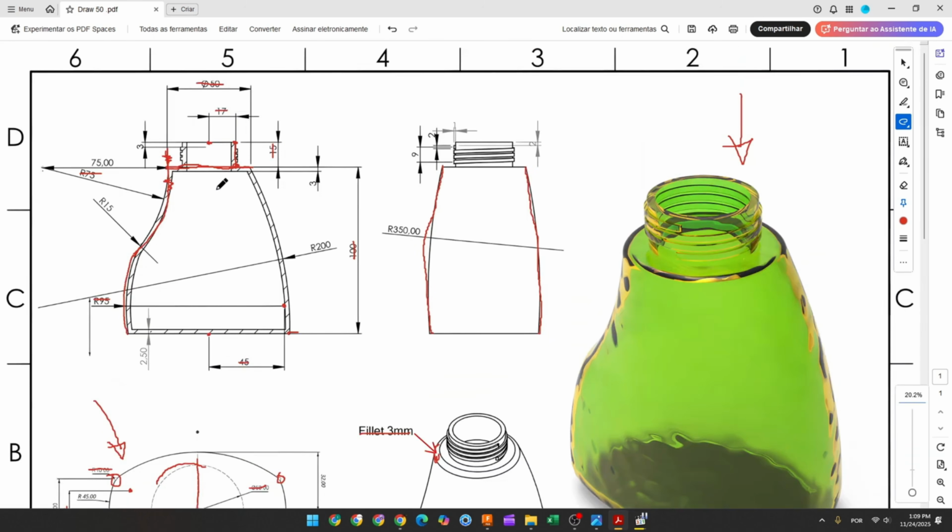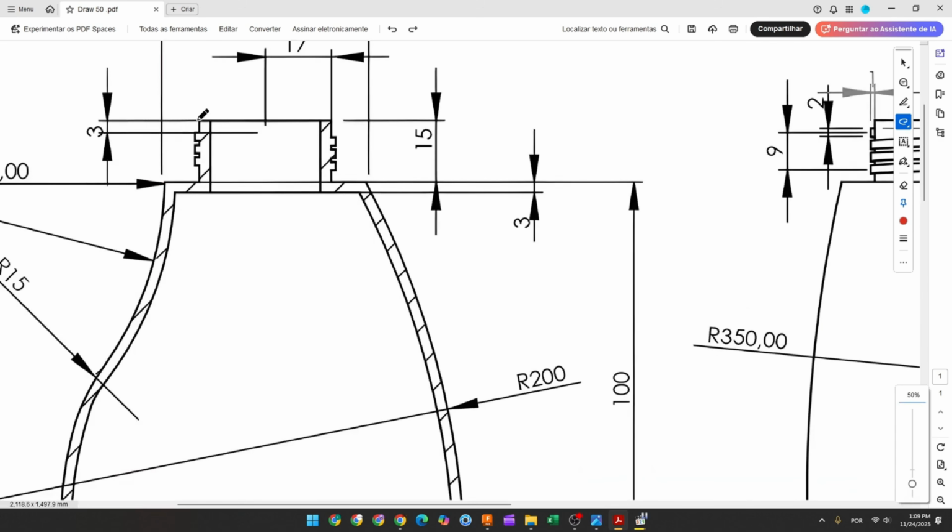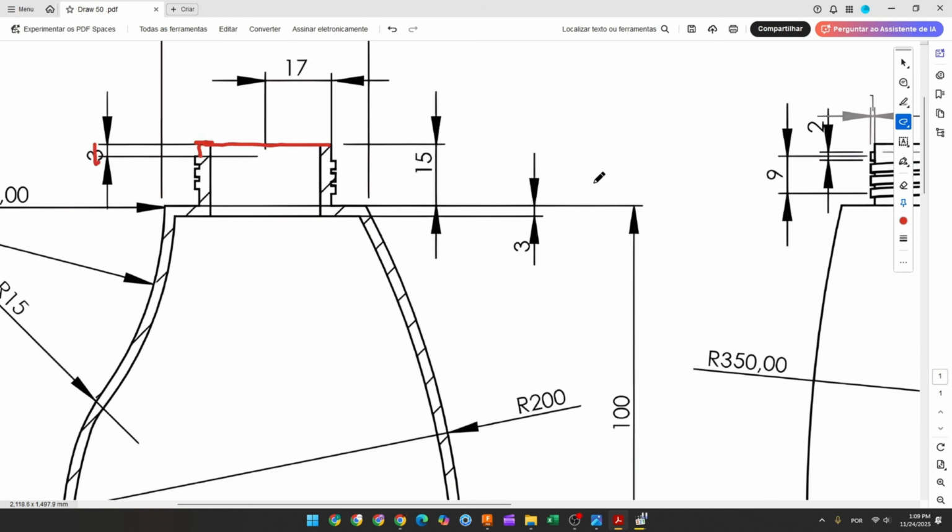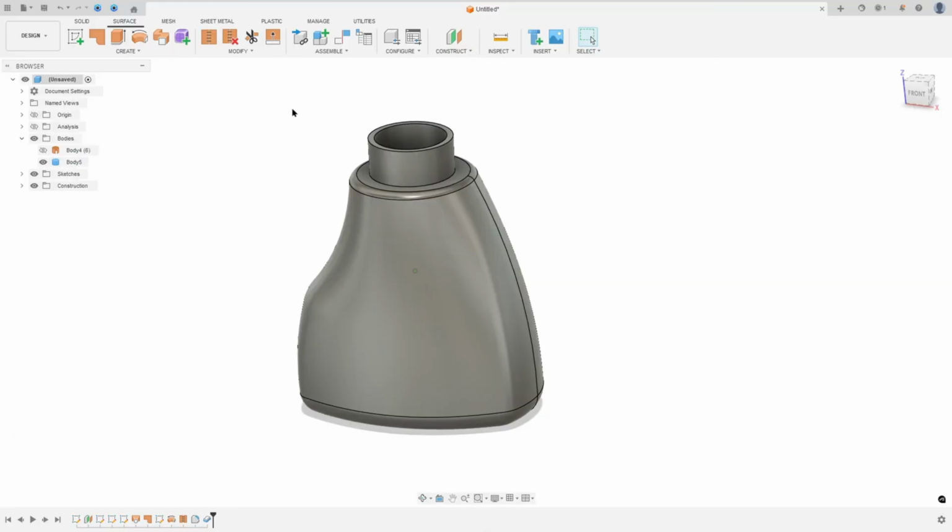Now we will make this 3D here, okay, on both sides. So to create this, the first thing that we'll make, we'll create a new plane with offset of 3 millimeters from the top surface here, okay? So go to construct, select this face, minus 3 millimeters, press OK.